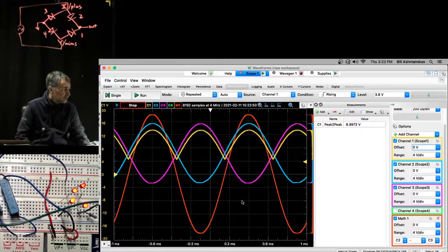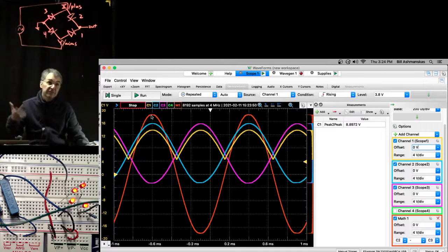And you see, the red curve is the math function. It is basically x minus y. So this is a sine wave with amplitude 18 volts. This is 4 volts per division, so it goes from minus 20 up to plus 20. So this kind of makes sense, because we have our two function generators together, 9 volts amplitude each.